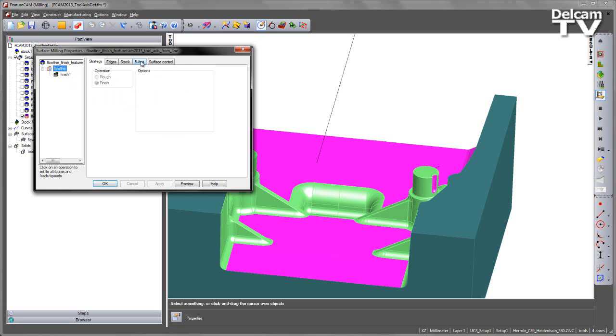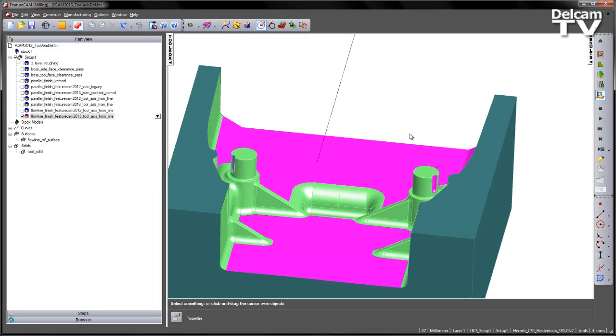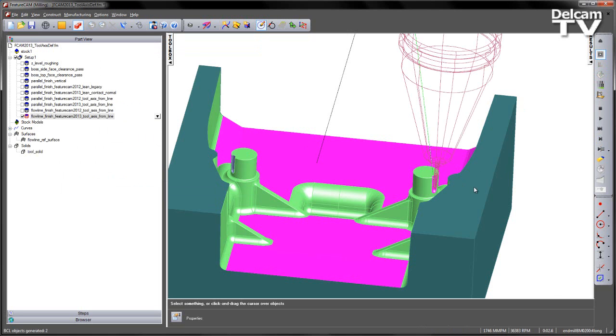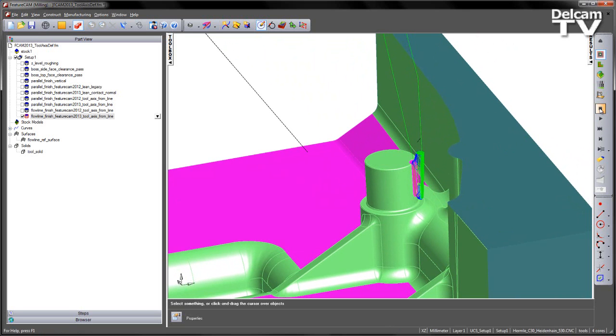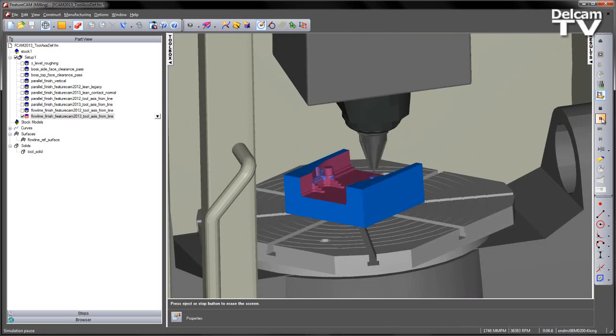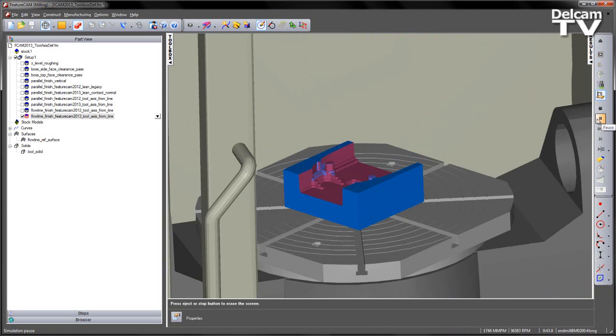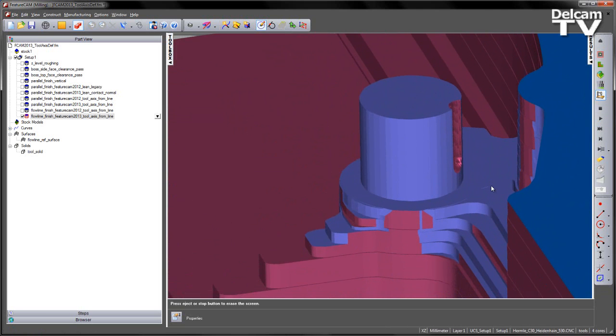If we use the new method, and again from a line, using that line orientation, and again I do a centerline, the tool now appears to be tilted over in the correct orientation. We can re-verify that on the machine. Playing that through and making sure that we have no collisions on our passes.